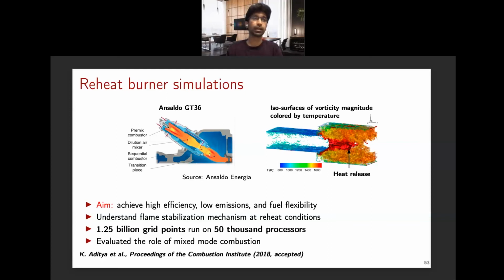The second combustor that you see takes the air from the first combustor, which is really hot, and stabilizes the flame typically using an auto ignition mode. And this stage is very important because this determines the overall efficiency of combustion as well as the engine operation.